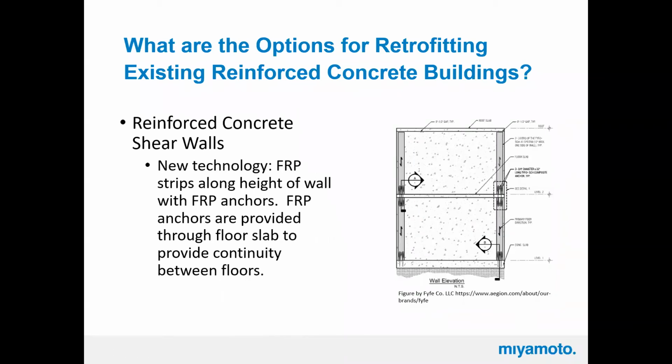And again, here's a diagrammatic of a kind of boundary element of a FRP shear wall. As you can kind of see these little things that look like fantails, they'll run those through the slab and anchor them to the slab below. So those are what creates the continuity in the FRP from one level to the other, and it works really, really well, surprisingly. Like I said, we've done that in a bunch of projects. I think Wayne and Pete and John Buckley did it at the CSI building in San Diego.